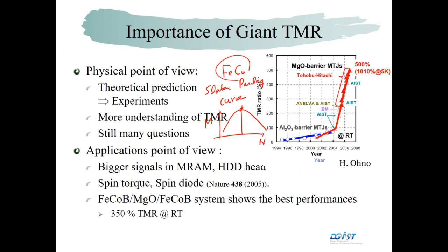Then what is the role of boron? The role of boron is not very clear because when we make the TMR structure with cobalt iron boron alloy, we then anneal it, and the boron is diffused out. So after annealing, we believe the cobalt iron forms a well-defined crystal. With boron, we can make the amorphous phase first.